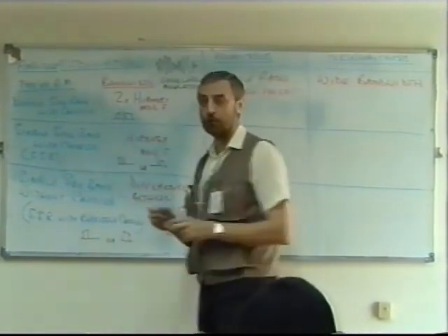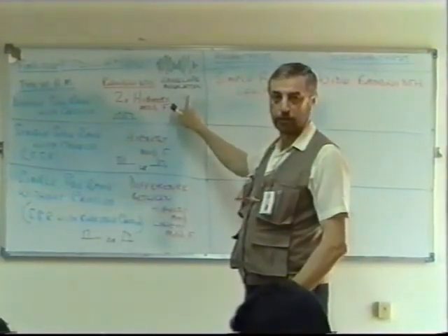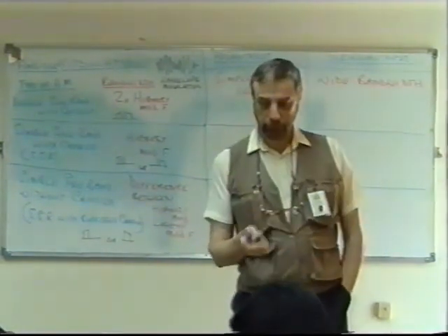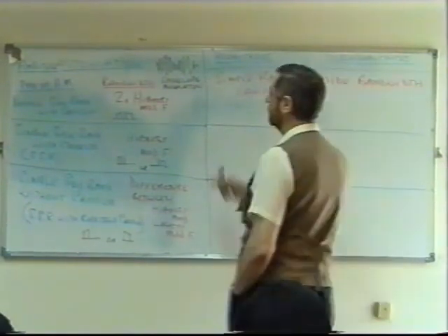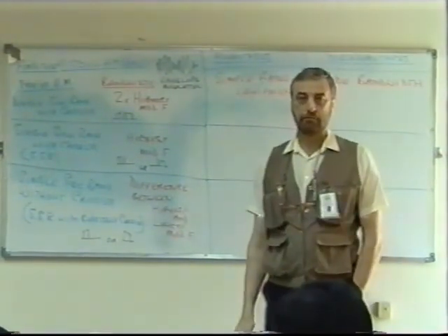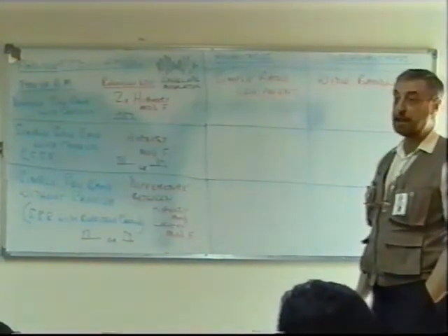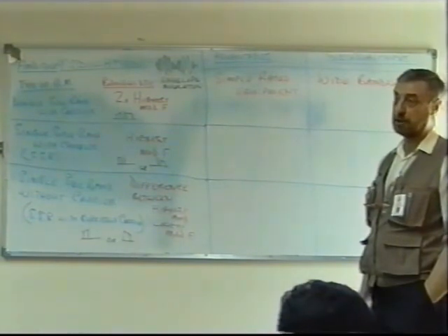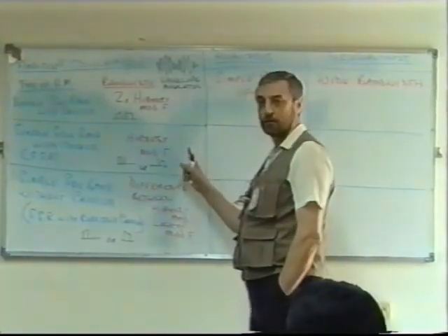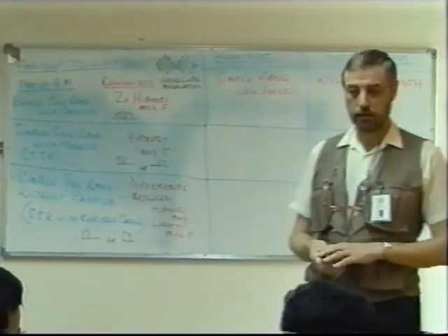You'll find that all broadcast AM signals are this type. All of them, yes. When you tune to the AM band of your radio, to the MF band, medium frequency band, and you tune into an AM signal, it'll be this type of modulation. But when it comes to telephone communication, say on the HF band, or telephone communication on the MF band, which is used by ships at sea, then they might use one of these other 2 types of modulation in order to save space and to get a better, narrower bandwidth.